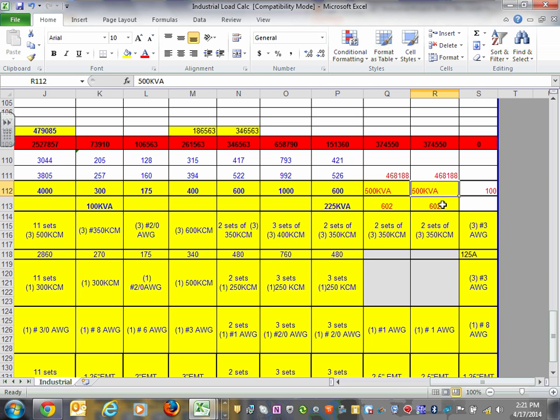I thought I checked. The PDU is 500, the same size. And then I found the amps for them on the primary side. PDUs, guys, especially the PDUs, have a transformer in them. I'm sure if you have dealt with them, they take the 480 inside a box that says PDU. You have a transformer in it, designed properly for the harmonics, and then they put together multiple panels, typically 2 or 3 panels in the same box. And they feed all these racks with 208 volt, typically 30 amp 208, and they feed all these racks.